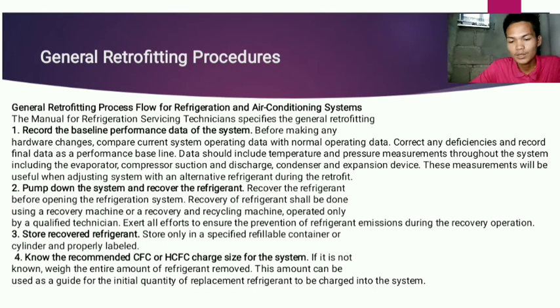Exert all efforts to ensure the prevention of refrigerant emissions during the recovery operation. Number 3 is store recovered refrigerant. Store only in a specified refillable container or cylinder and properly labeled.